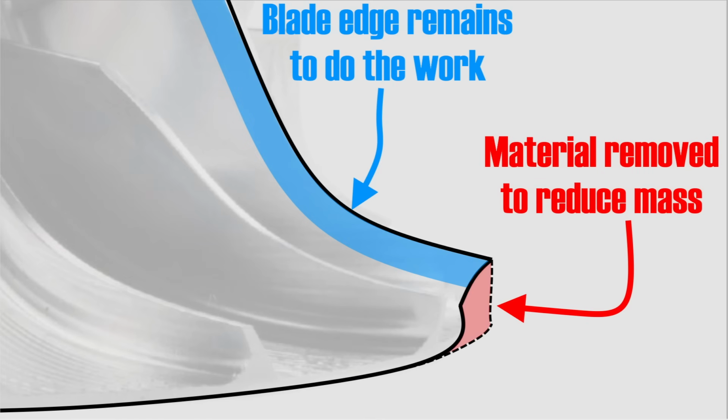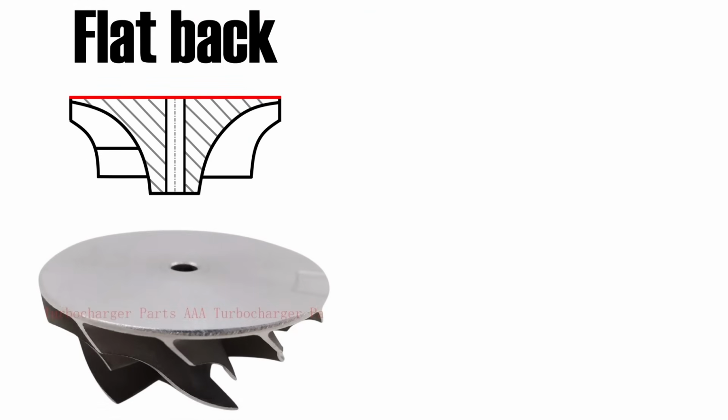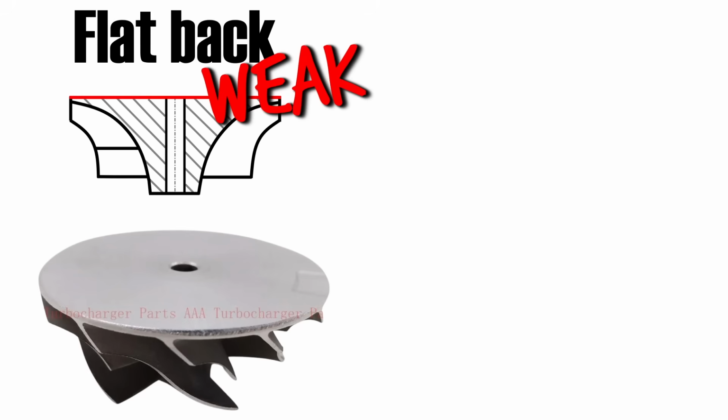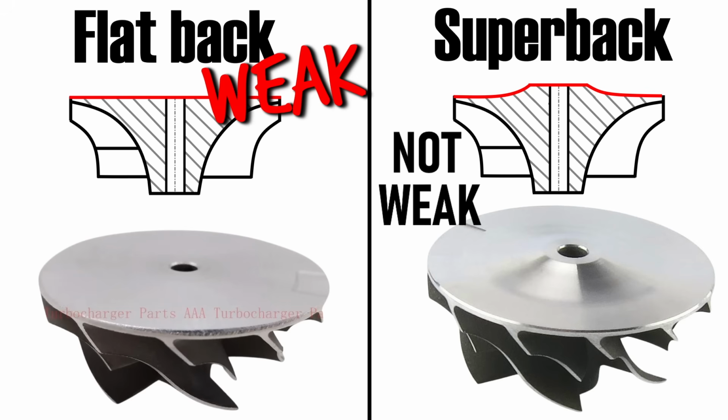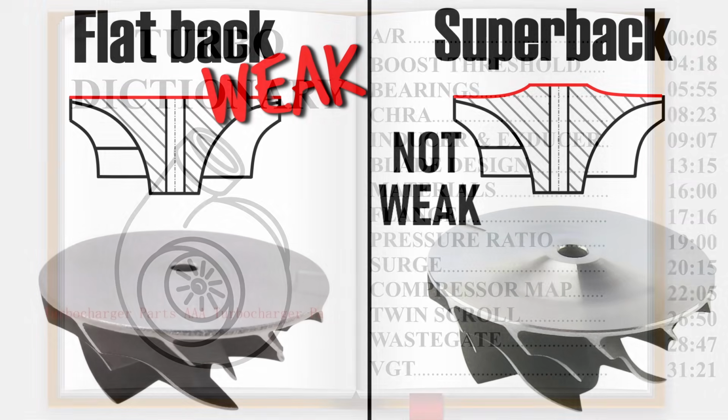Another major improvement in compressor wheel design has occurred on the back. Early compressor wheels employed a flat back design. This design demonstrated an inability to deal with the stresses of high RPM and high boost pressure, which caused flat back wheels to fall apart. A super back design increases the amount of material at the base, which dramatically improves strength without increasing the weight too much.